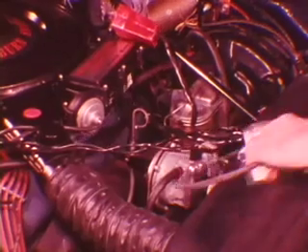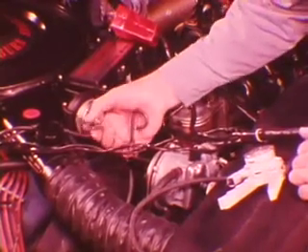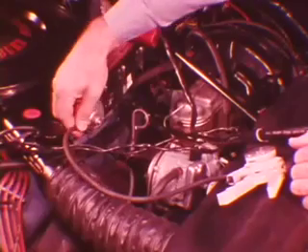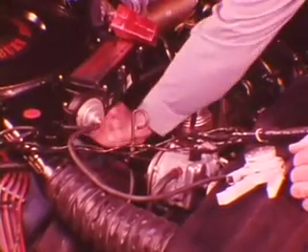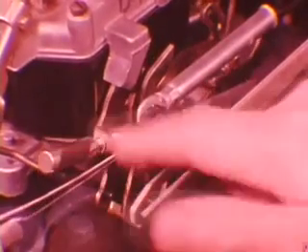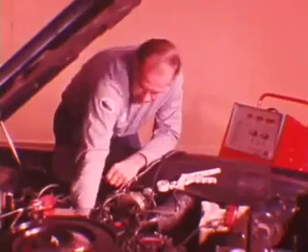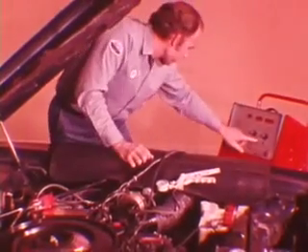When code 6 appears, you'll pull the hose from the computer vacuum transducer and connect a hand-operated vacuum pump. But be sure not to pump any vacuum until you're instructed to do so. Check to see that the throttle is off the fast idle cam, and press the continue switch.